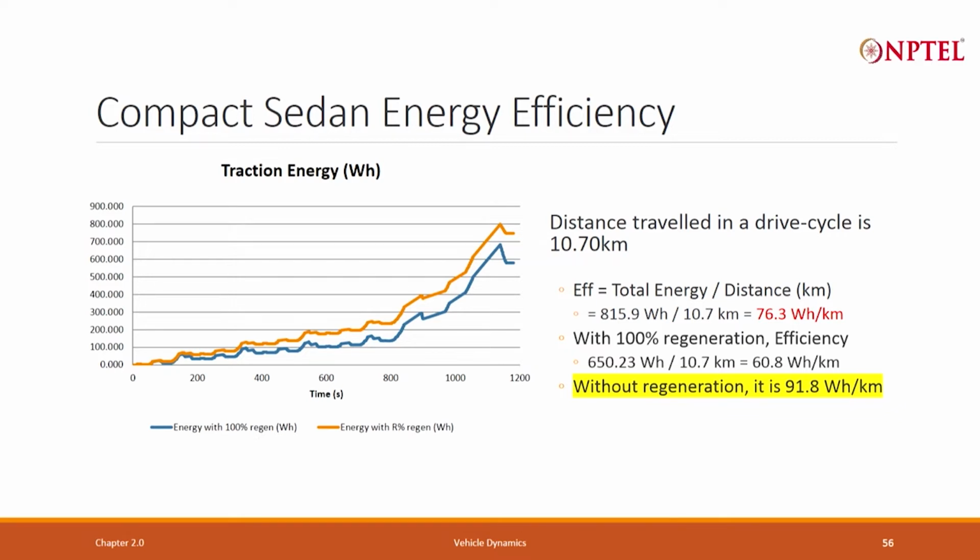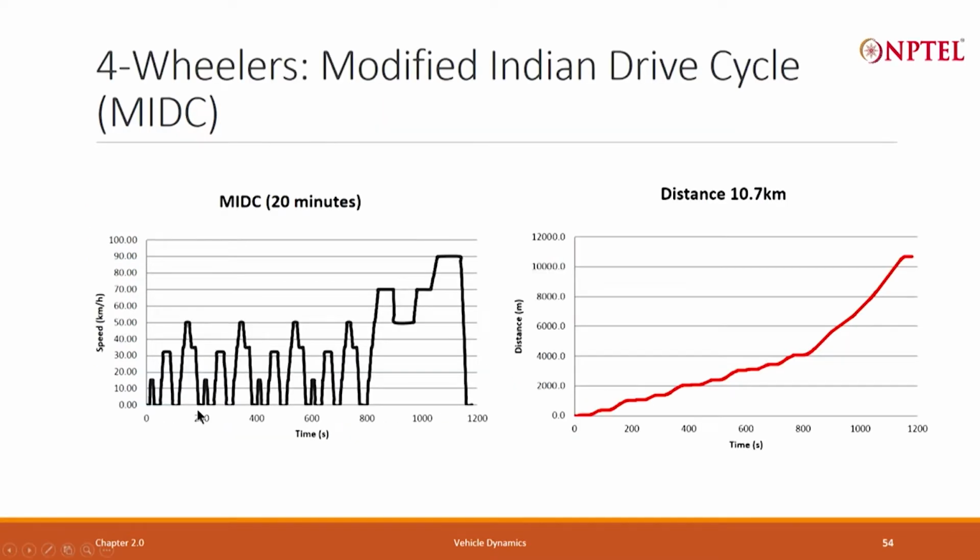It actually uses an induction motor. This is a version 1 of electric Verito. It uses an induction motor, which at high speed gives me all right efficiency, but at lower speed gives me very poor efficiency. And since most of the time I am actually travelling at lower speed, look at this, that is what the city drive does. On campus I always travel at lower speed, I do not even ever go to 50 km/h. It gives a very poor efficiency, and that is the reason.